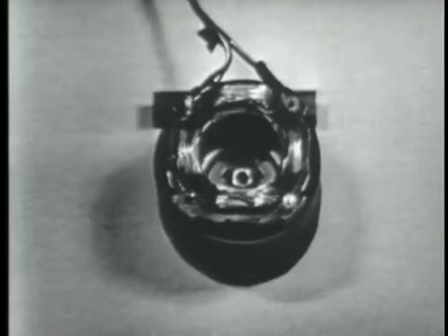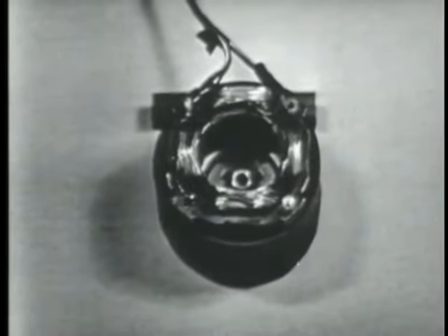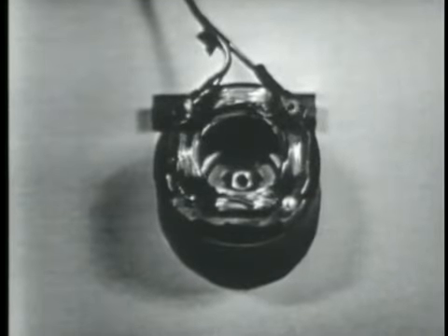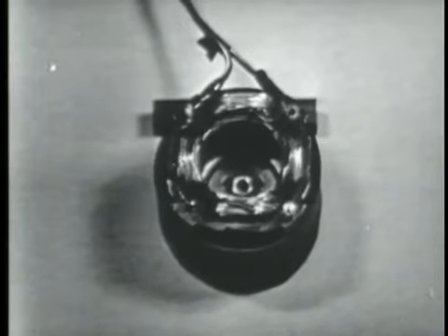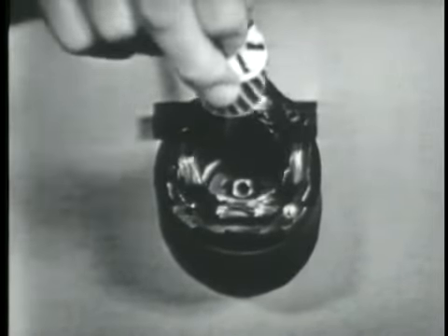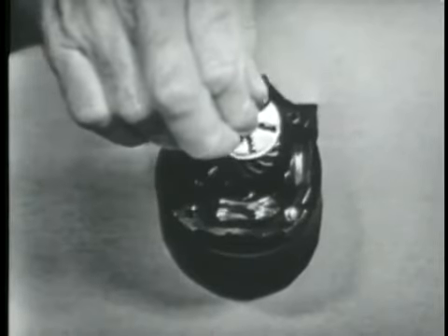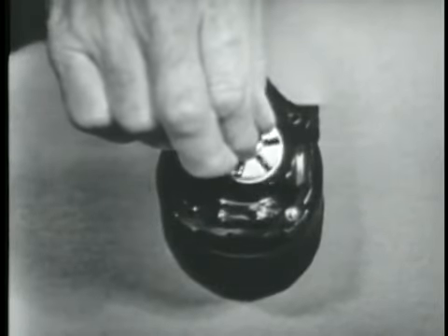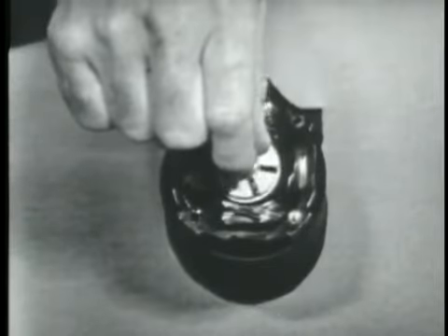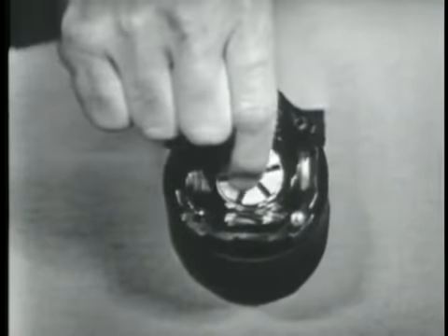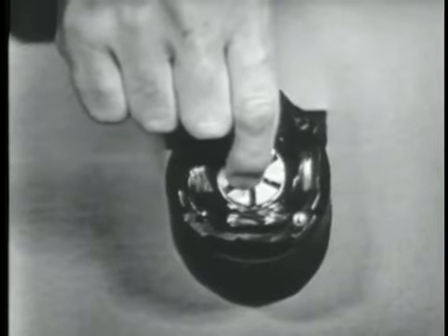I'll start over. These field windings have AC applied to them in the proper phase relationship. They are producing a rotating magnetic field, which is easily proved when this chunk of iron is dropped into the field. Well, proved, Tom, not really easily, because the magnetic field is attracting the rotor toward the stator field. We've got it in there now, and if I let go of it, it rotates.